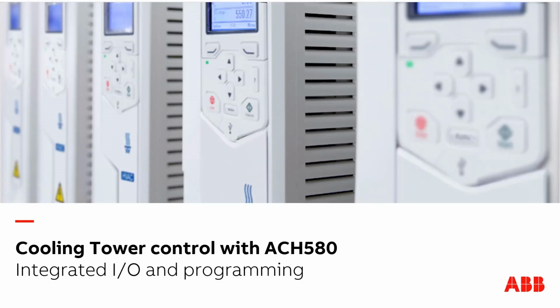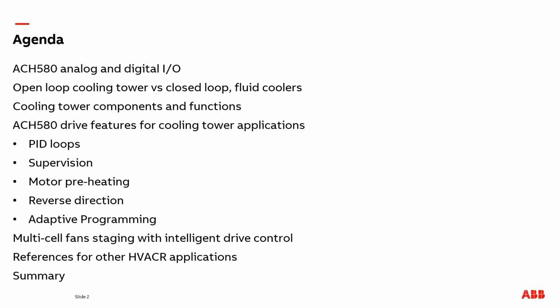In this video, I will cover some basics of cooling towers and the features available with the ACH580 series of drives and integrating controls for cooling tower applications. For this video, I want to start by reviewing the analog and digital I/O available with the drive and applicable for cooling tower programming. Then I'd like to step through different system types for cooling towers, their components, and basic functions. Then we'll review several of the drive features available for integrating cooling tower control into the drive.